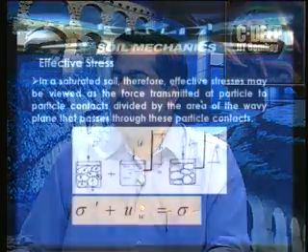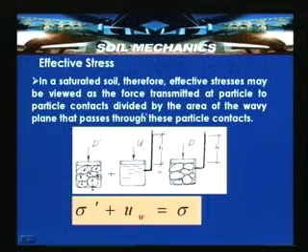Here in this slide we applied the laws of statics to a soil element in equilibrium, and deduced that total stress is equal to effective stress plus pore water pressure. So, from this slide and the previous discussion, in a saturated soil, effective stresses may be viewed as the force transmitted at particle to particle contacts divided by the area of the wavy plane that passes through these particle contacts.